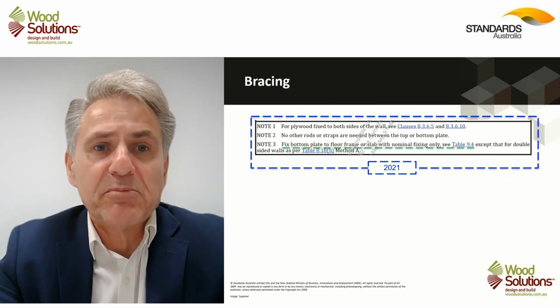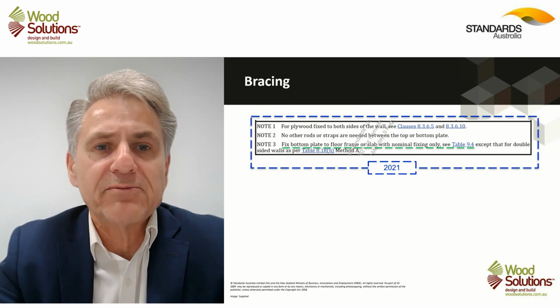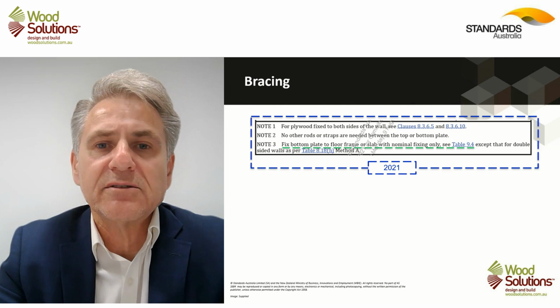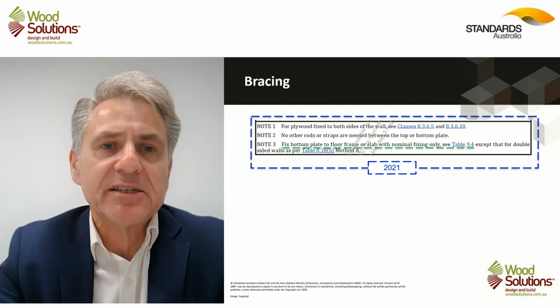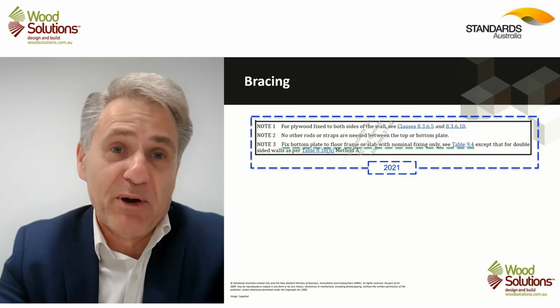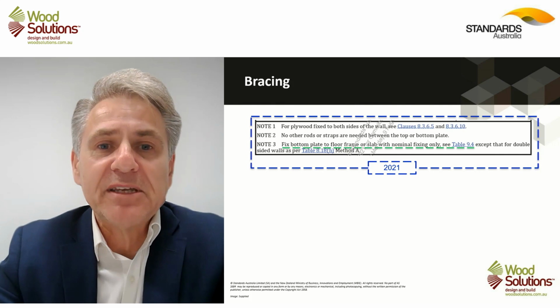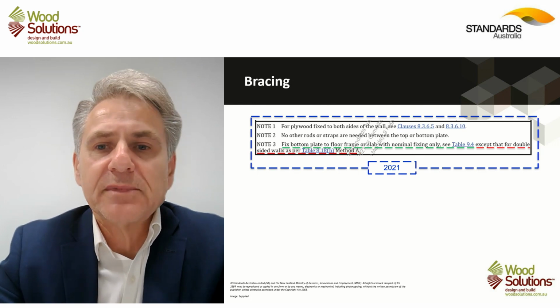Basically, with that plywood brace, you can just use standard bottom fixings or nominal fixings to that bottom plate. But with these plywood brace systems, there has been a tendency for people wanting to brace or plywood sheath both walls, and that can be done. And it basically directs you to method A under that 18H example.